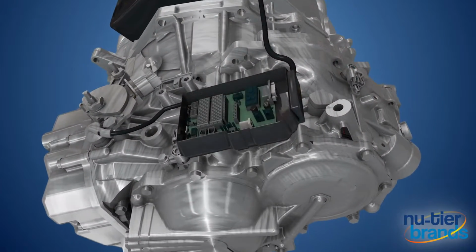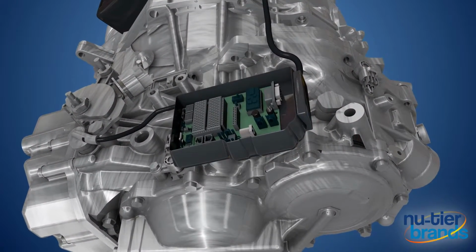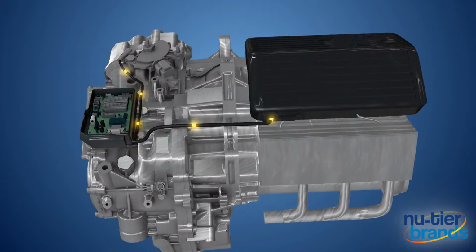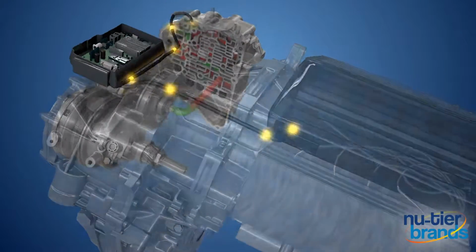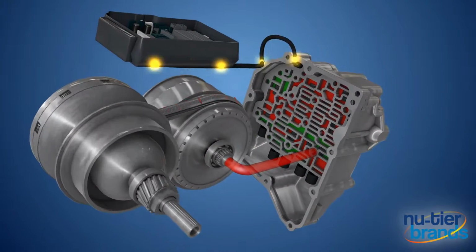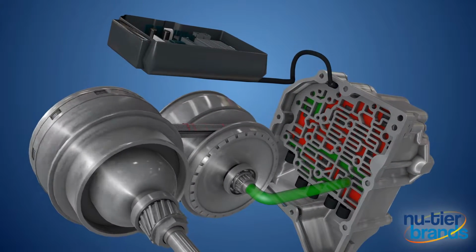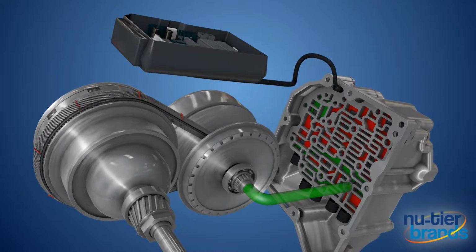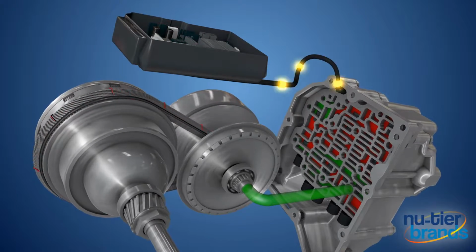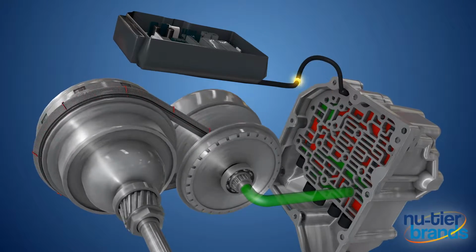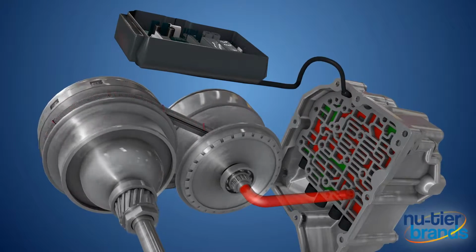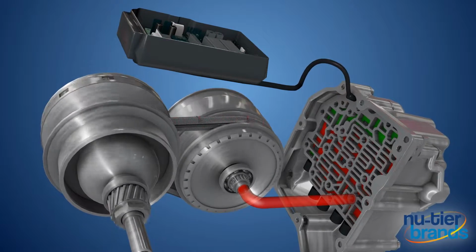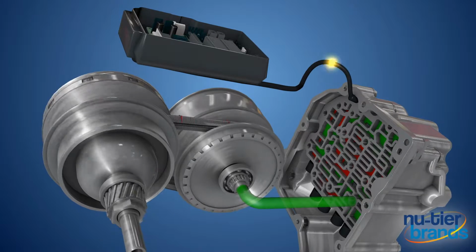The Transmission Control Module, or TCM, is the brain of the transmission. It communicates with the Engine Control Module to analyze changes in operating conditions, then fine-tunes the CVT's gear ratio to operate with maximum efficiency. When the engine is idling, the CVT rests in low gear. As the vehicle accelerates and more load is applied, the TCM recognizes this change and adjusts the pulley positions accordingly. And this is a smart system. It can even learn from previous driving conditions.